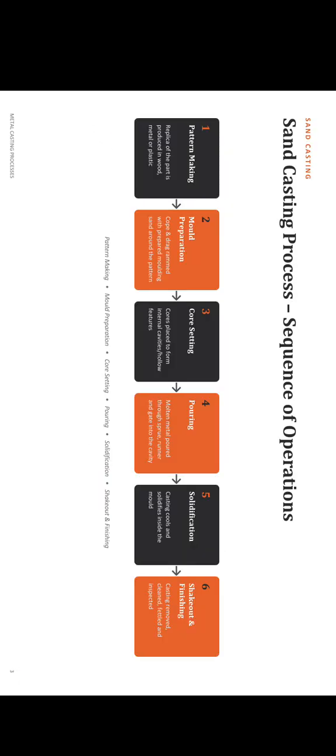Sand casting process. The sequence of operations: first, pattern making, mold preparation, core setting, pouring, solidification, shakeout and finishing.